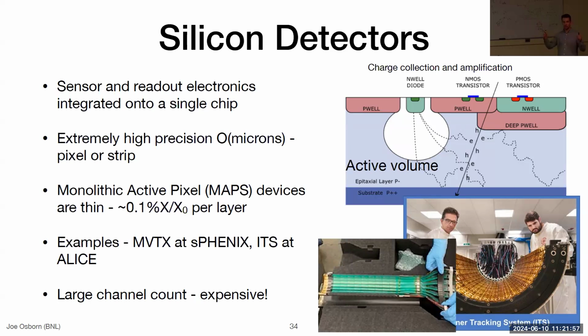1 direction. So there's a strip direction that has a very large resolution, typically of order of a millimeter or something like this. And then in the strip detector, you have the other pitch, which actually gives you order tens of microns resolution. So the really great thing about these silicon devices, which you'll hear a lot about, MAPS detectors, MAPS are monolithic active pixel devices.